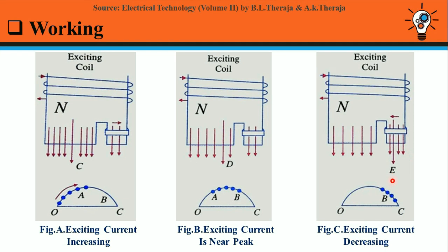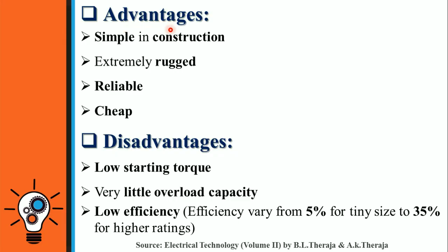From all the discussion, we find that as time passes, the magnetic axis shifts from left to right in every half cycle, that is from unshaded region of the pole to the shaded region of the pole. This gives to some extent a rotating field effect which is sufficient to provide starting torque to squirrel cage rotor and rotor rotates.